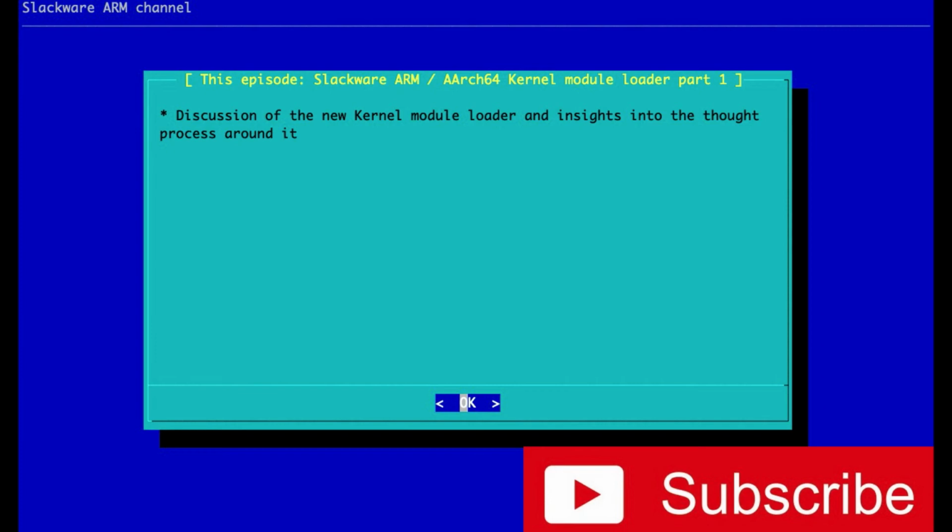If you put U-boot back onto the SD card as a header, then when the SPI flash is jumpered, it's bypassed, and the Rock Pro64 will boot U-boot from the SD card. So then you can boot the installer and reflash, and then take off the pins. Or the other way, you take off the pins before you flash it, because I think the pins mask out the flash, or they prevent you from accessing the flash in the first place. Well, if you're just reflashing using, as an example, an SD card that has U-boot to reset U-boot, you don't need to jump it. I don't believe you need to.